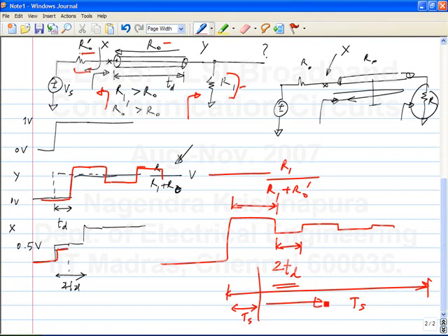So this also creates intersymbol interference. And of course, the intersymbol interference becomes particularly annoying when the impedances are different from the characteristic impedance. That is, the transmission line is not terminated very well. In that case, you will have a large amplitude of reflection, so you will have a large amount of intersymbol interference.